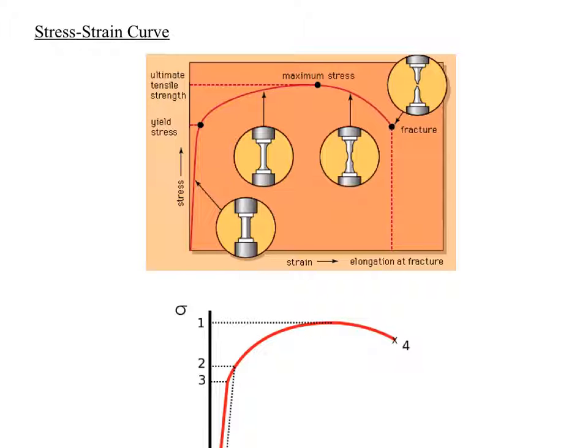So when that happens, it continues to stretch more and more, and more stress is applied until the material can no longer even hold that stress. So the machine lowers the stress applied until it fractures, until it fractures at the very end. And that's where that snapping occurs. If you've ever seen this, and I'll show you a video of it, but in person, it's actually kind of cool. You can watch the specimen, you'll see it start to narrow in the middle more and more.